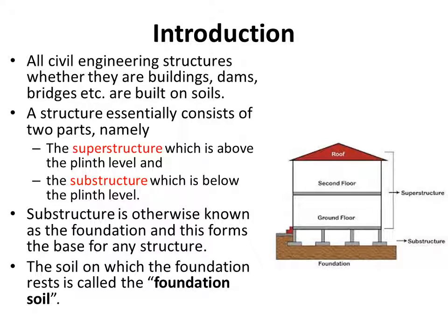As we know, all civil engineering structures, whether they are buildings, dams, bridges, etc., are built on soil. A structure essentially consists of two parts, that is the superstructure, which is above the plinth level, and the substructure, which is below the plinth level. The substructure is otherwise known as the foundation, and this forms the base for any structure. The soil on which the foundation rests is called the foundation soil.